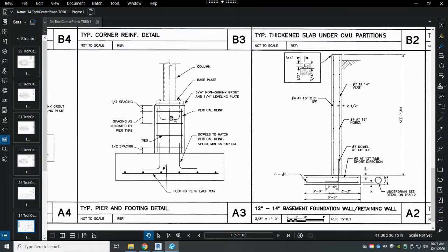The reason for that is that height information, remember, is in the plan view that shows all of those height callouts based off of 0 feet, 0 inches of the slab elevation. So that's why we're not seeing any height information for this part of the pier. But we are getting some spacing for rebar and knowing where our column base is, and then our actual steel column is going to be supported by that pier. This pier is being supported by this footing.